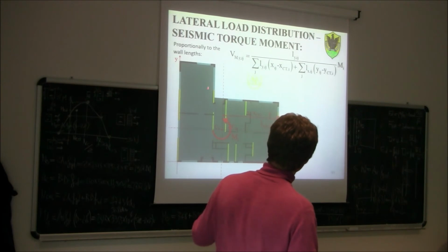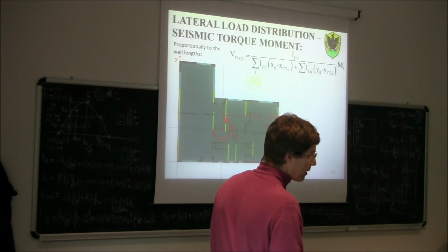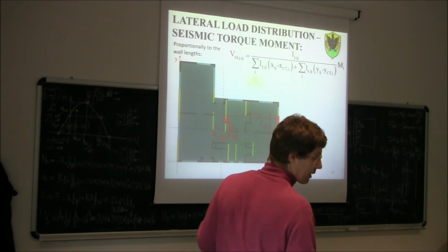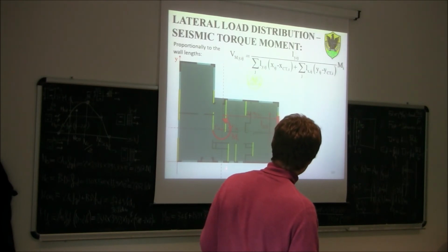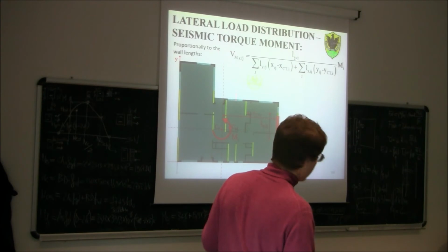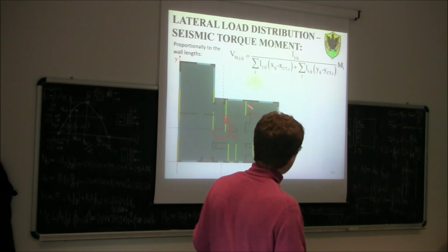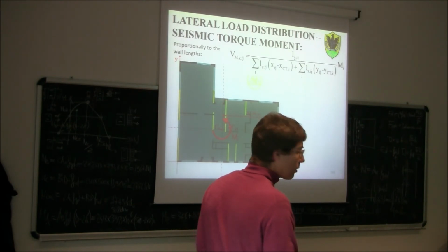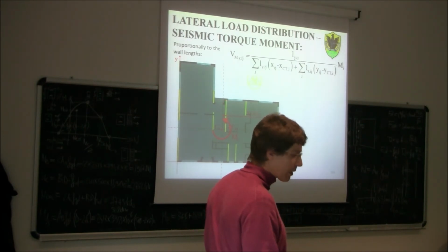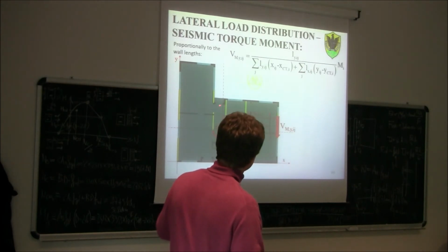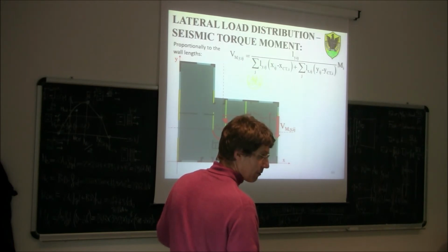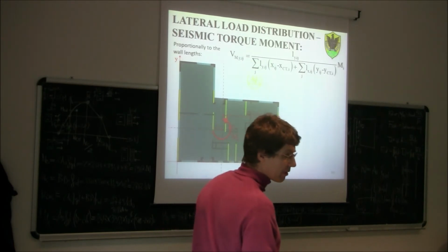No, because in this case, while before, for let's say for the seismic force applied in one direction, for example, for the seismic force applied parallel to y, only the yellow walls are active. Instead, when you apply a bending moment, a torque moment, all the walls are active. Because you see, for example, in order to get this torque moment here, I have to do this seismic force here times the distance, plus also this force here times the distance. Yes, all of them must be consistent, exactly. Okay?